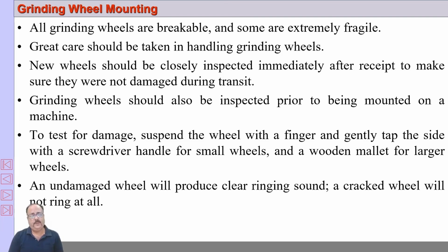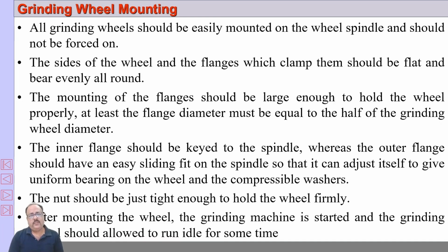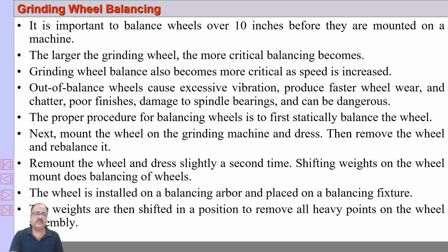So it is very important to test the grinding wheel and mount it properly. Normally the foreman does the grinding wheel mounting in any kind of machine shop. So grinding wheel mounting is very, very important. I have listed out some steps on how to mount the grinding wheel. You can go through this. Balancing also is important. Out of balance may cause accidents. So the grinding wheel has to be balanced properly before it is mounted. Wheel balancing and wheel mounting are two important aspects in the grinding process.